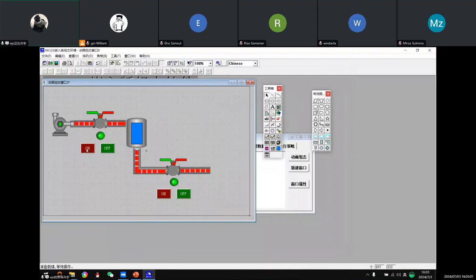We press down the on button, and the value of feed will be set to 1, meaning the valve is on, and one of the green or red bars will show up and the other will disappear. Also, the indicator will appear red or green. The discharge one is the same as the feed one.